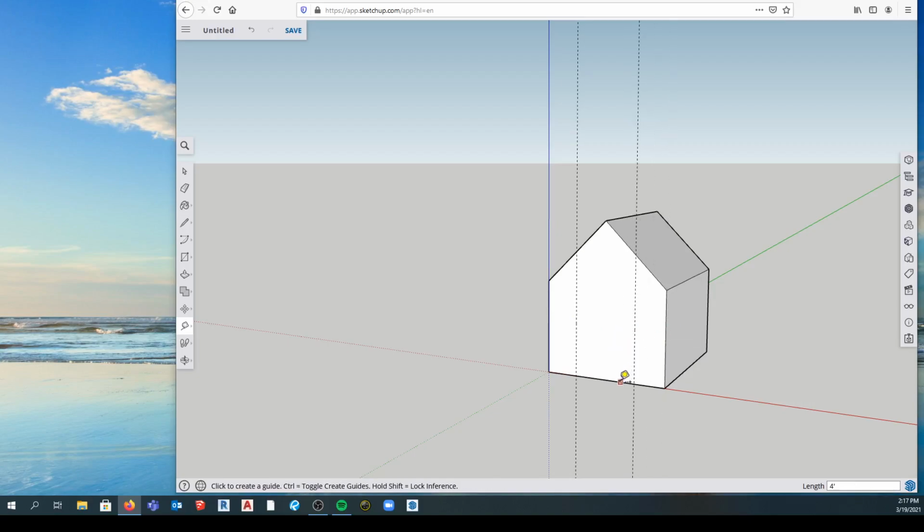And then I'm going to pull this one up. I'm going to hover over this edge and pull that one up 2 feet. So right now these are not lines, these are all just guides. So then I can draw a rectangle again. I can now take that rectangle command and I can just snap from guide to guide. So now I've got this sort of face on my doghouse, which I think is pretty cool.